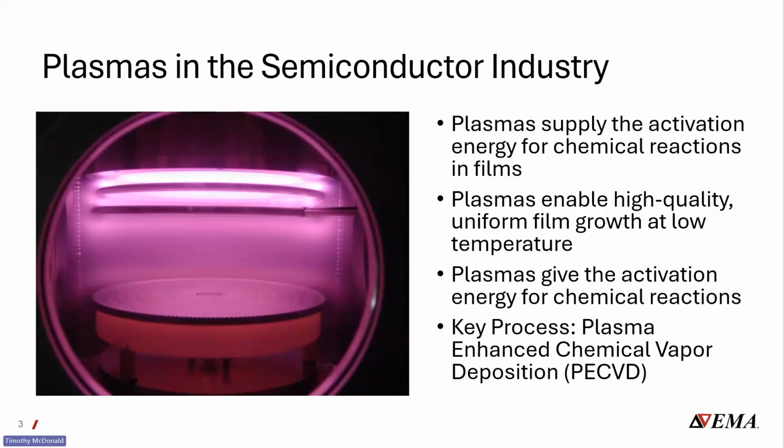So first, let's talk about plasmas in the semiconductor industry. Plasmas are essentially supplying the activation energy for chemical reactions in films. The key thing is the thermal limits. As devices get thinner and stacked, think 3D NAND, FinFET, gate-all-around, wafers themselves cannot withstand repeated high temperature steps. It makes sense, right? As they get smaller, it's hard to survive that big temperature.